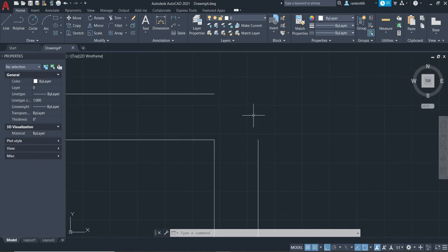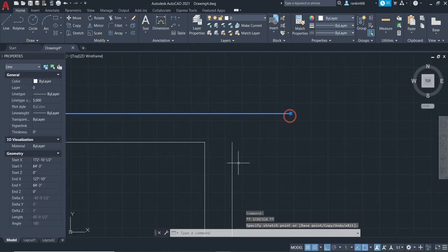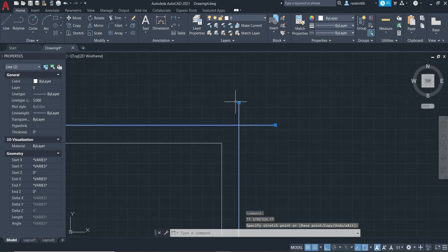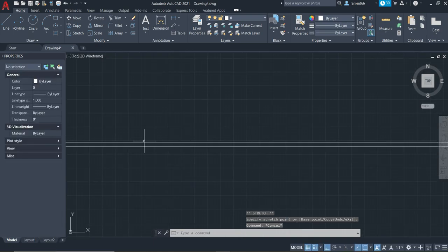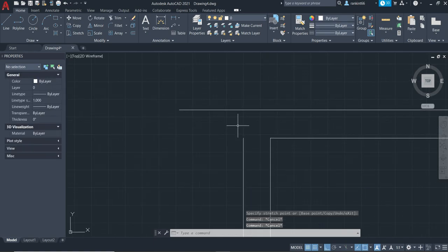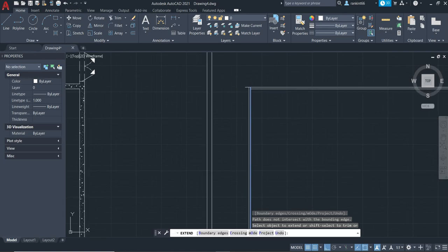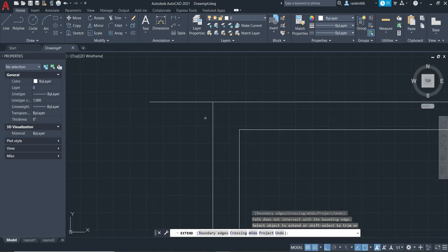The next thing I want to do is, you'll notice here, I need to kind of fill in these gaps that are missing here. The first step I'm going to kind of do is I'm just going to stretch these out. You can see you can grab it and just stretch it along as long as you have, again, that orthogonal view, so it's drawing just up and down, left and right, like it's locked to those positions. You can kind of just draw it up and through. And then you can trim these pieces out really easily. Or you can draw these across, and you can use the extend tool. So I'm going to just type in extend and hit enter. And now that I have that drawn, it'll automatically clip up to that, and I have it there, and I can just trim that portion off.